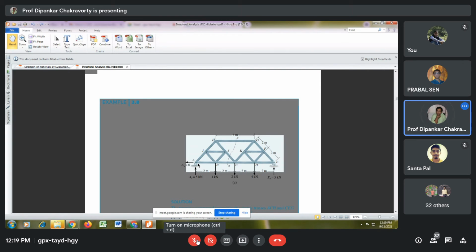AI and AB. Very good, the forces in AI and AB can be solved. Then which joint do you want to go to? If you go to joint B, you see there are three unknowns. BA is known, but BI, BJ, BC are unknown. Am I correct? Yes, sir. If you come to joint I, IA is known, but IB, IJ, IH are unknown.